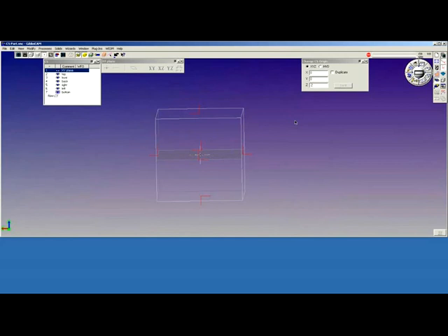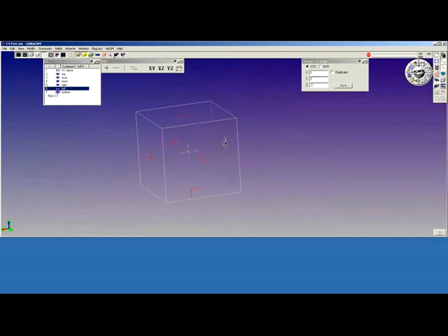Now, once I've verified, then I'll go ahead and turn off the eyeballs, because the frame indicators not only indicate the direction of the axis, but they can be used for toggling between coordinate systems. If I click on this frame indicator, it takes me to that coordinate system. And you can navigate the coordinate systems by clicking the frame indicators. Now, this is really handy, but if you've got geometry on screen and you're selecting for machining or modifying, sometimes the frame indicators get in the way and you end up changing coordinate systems inadvertently.